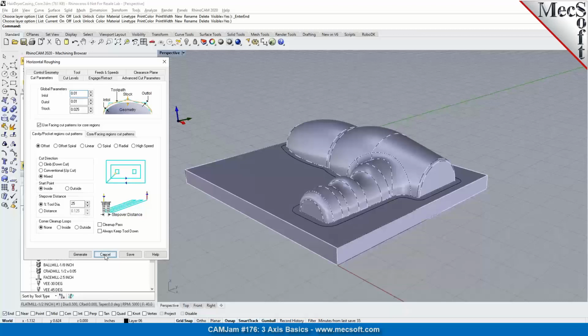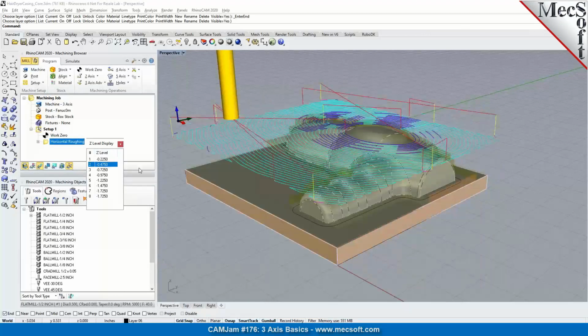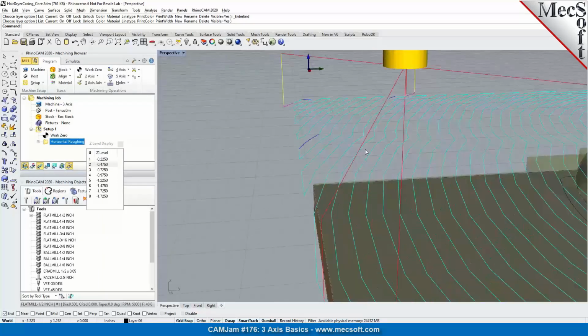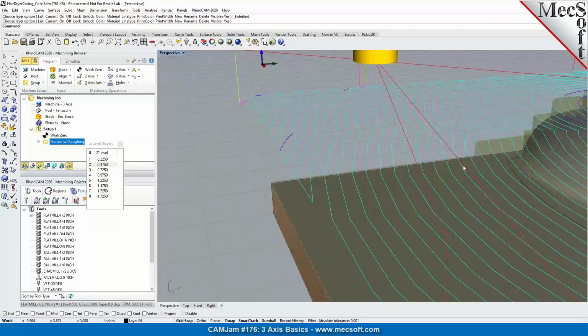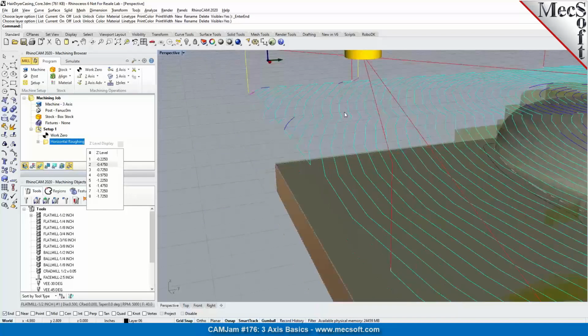As you take a look at this particular toolpath that we generated, if I step down to levels here, you can see that the slacker the tolerance that you've set, the deviation is within the tolerance, and you'll see the chord segments, the toolpaths are much more faceted in here. So the tighter the tolerance, you'll have much smaller chord segments, which maintain it within the accuracy of the tolerance that you specify.